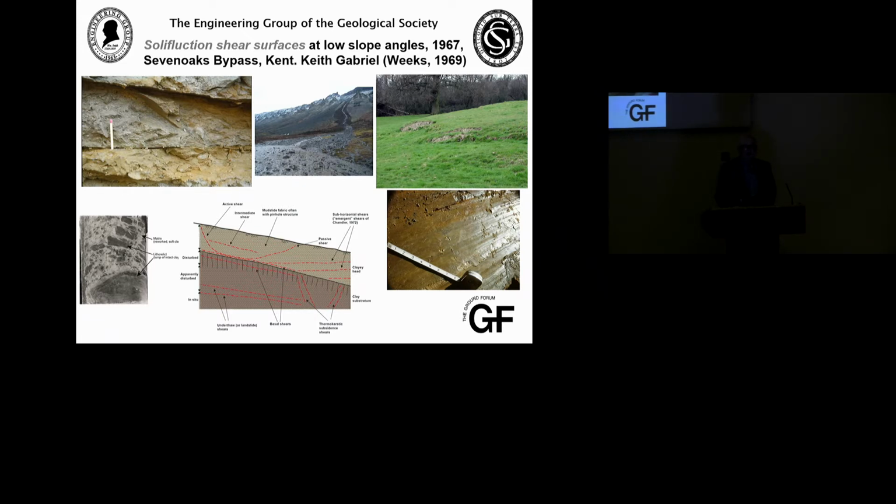We had 2 field trips while we were doing the working party. First of all, we went up to Scarborough, and we saw this variety in tills that we'd never really seen before, and dispelled the myth of boulder clay, dispelled the myth of lodgement till. And then we went down to Sevenoaks. The Sevenoaks bypass is really a seminal case study in engineering geology. It's one of our holy grail case studies where perhaps for the first time we discovered solifluction lobes, and reactivation of shear surfaces.